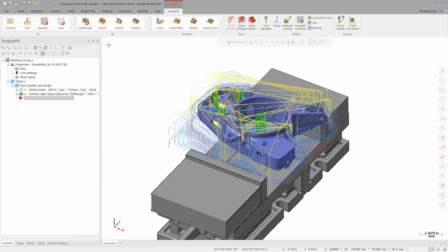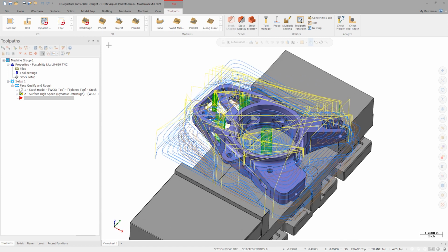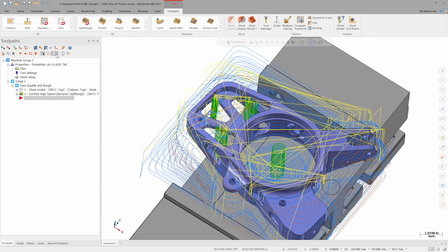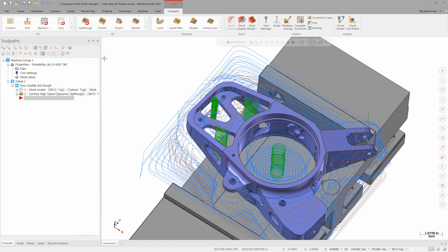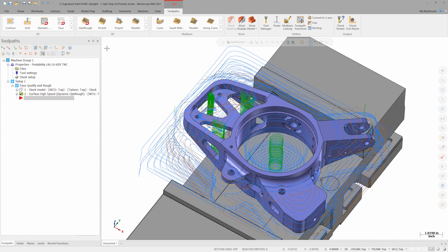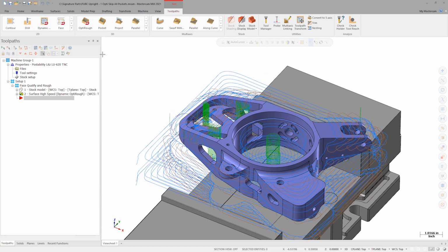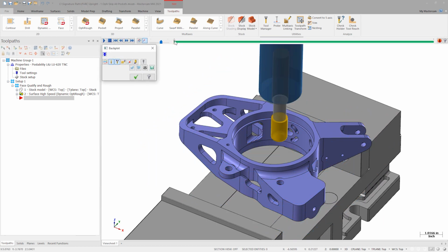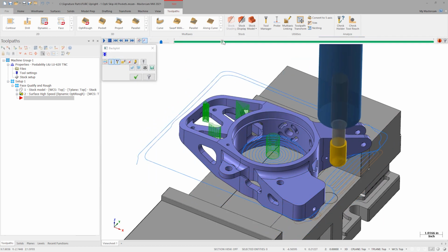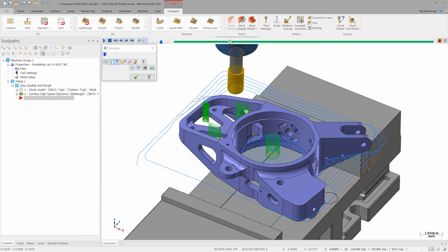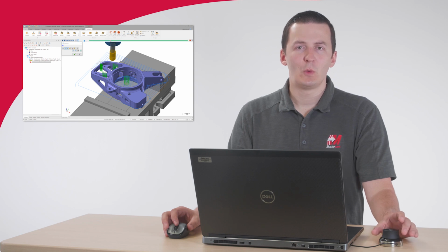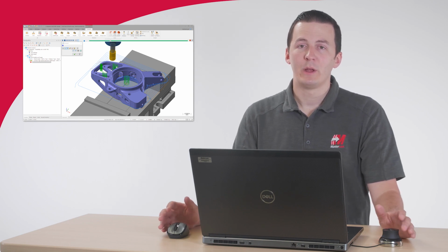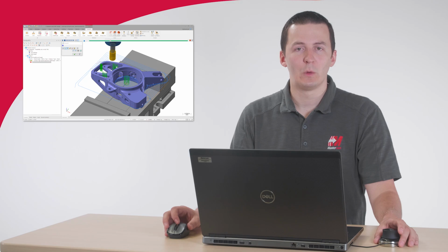We already have an OptiRough toolpath created on this upright. If we turn off the rapid retract motion on the advanced toolpath display dropdown, we can see all the entry periods shaded in green. If we open backplot, we see that the toolpath doesn't start dynamic roughing from outside until after it enters 4 pockets. Because of this, the tool may be somewhat worn or even damaged before getting to the main portion of the toolpath. This behavior makes this toolpath a perfect candidate for skipping pockets.